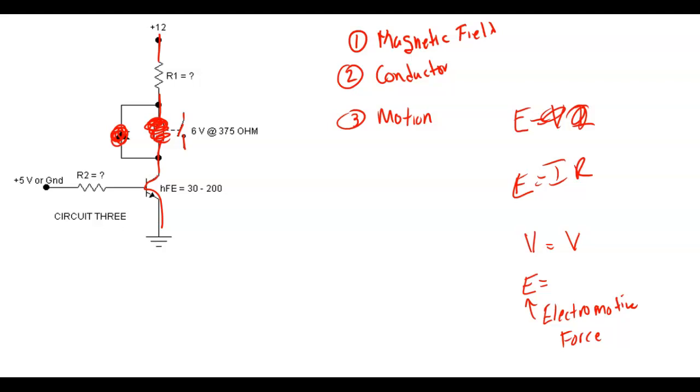So here I've got a coil. This would be simulating the relay. And what I'm going to do right now is see how much voltage it takes to turn on a gas bulb. This is a neon bulb. It takes a lot of voltage to turn them on. I got my meter on there. Right now I got 11 volts across the bulb.